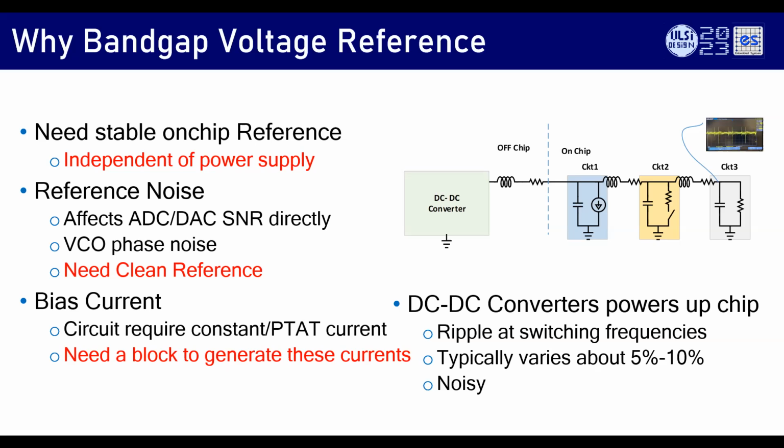That is one problem. Second problem is this percentage depends on the temperature. When the temperature changes, you may get 1.05 volt at minus 40, you may get 1 volt, at 27 you may get 0.95 volt. It's all possible. And on top of it, the voltage also depends on how much current you draw from the DC-DC converter. No DC-DC converter has an output impedance of 0. It has a finite output impedance, so that voltage keeps on fluctuating. So what? So you're not going to get a proper reference voltage on chip if you tap from VDD. The reference voltage itself will have a plus or minus 10% variation. So why is this a problem? What is the problem if the reference varies 10%? Let's say.